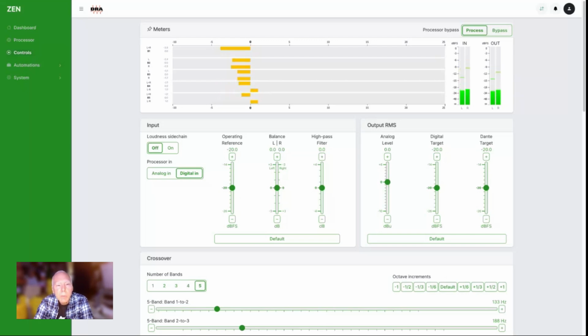You see, in this case, we're using 5 bands of gain, and to the left means the gain is decreasing, and to the right of the 0, the gain is increasing. So this would be band 1, band 2, band 3, band 4, and band 5. The color and the position of the band indicates the amount of gain and the activity of the processing.